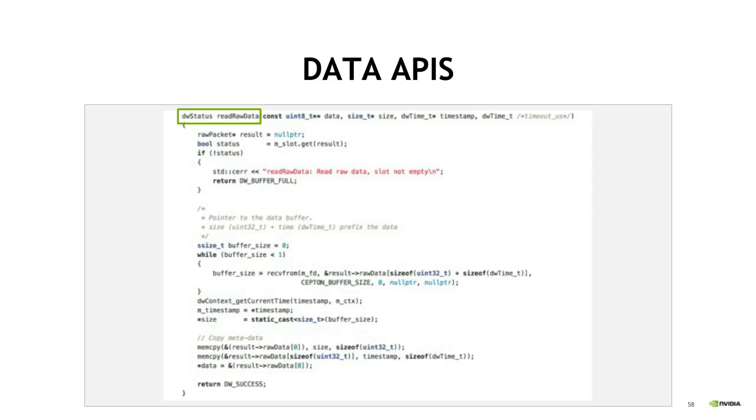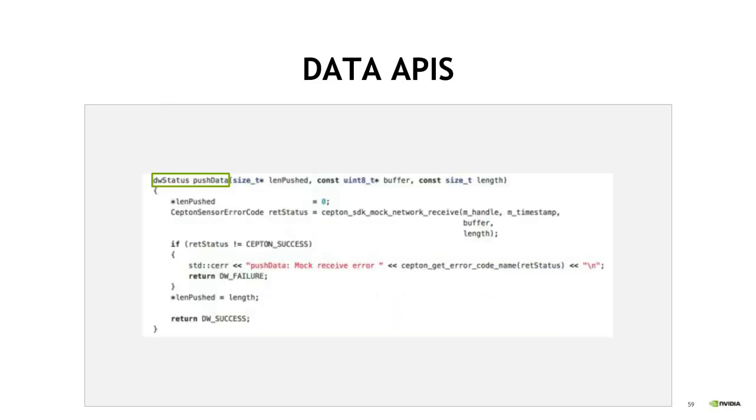After collecting the raw data buffers from the read raw data API, SAL will call push data inside the plugin. The push data function gives us the capability to collect the raw data into a buffer when a single sensor message doesn't translate to a decoded message. In our implementation, we push the received bytes to the Cepton SDK that will perform decoding for us.